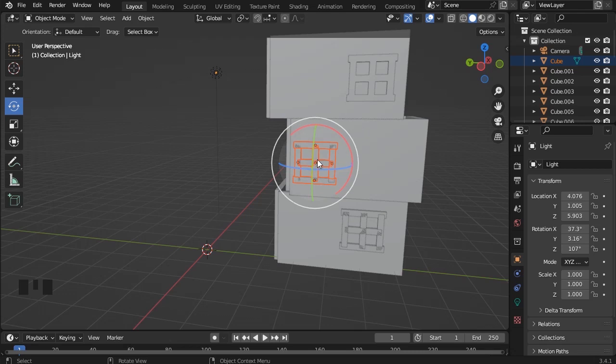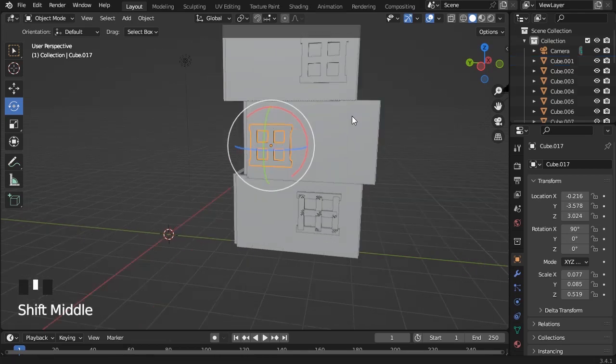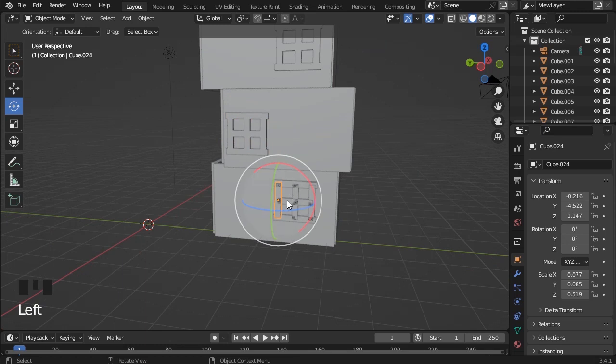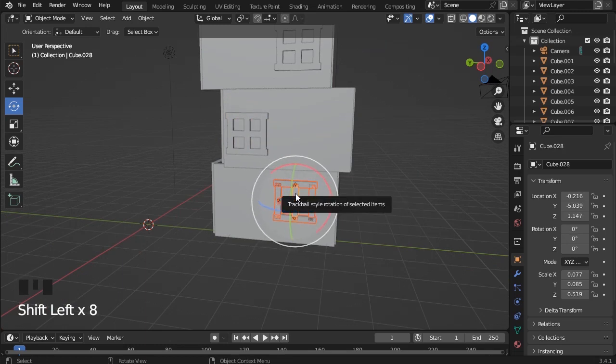Like all of this is orange, and then they try to click Control J. It will not connect, because there's nothing that's set as origin. So you have to make one part of it yellow to press Control J, and then it's connected there. Okay? So you have to select, and then you at least have to leave one part of it yellow, and then you click Control J, and it'll be connected.